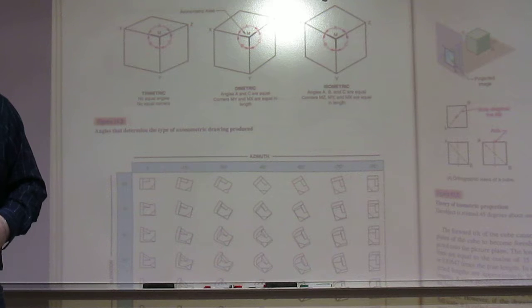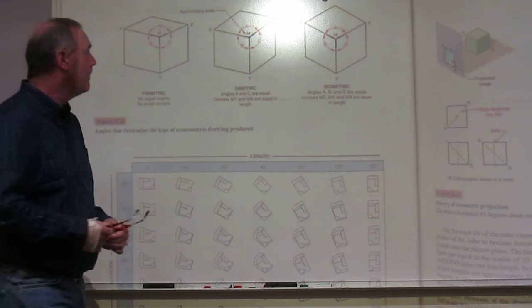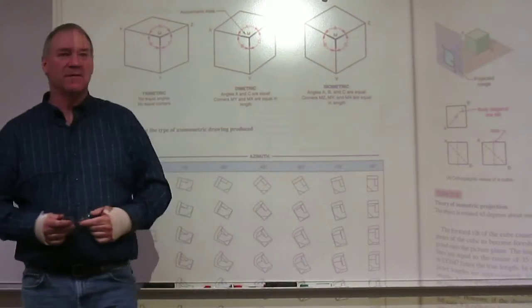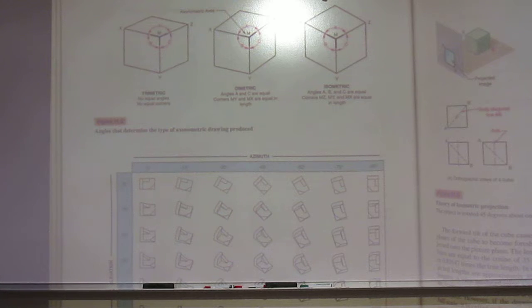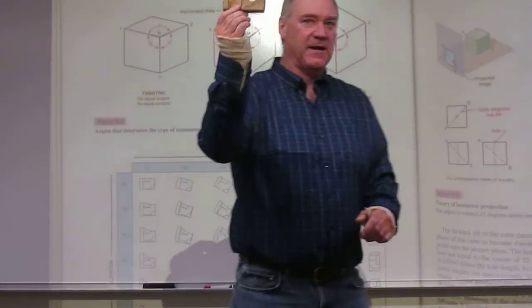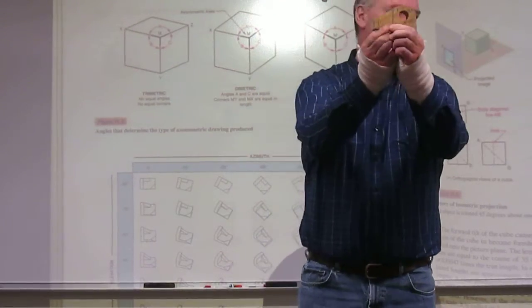What is the angle on there? Angle ABC. Remember, it's a full circle, 120. Now, how they get that is they're using orthographic projection to produce this. Remember, you'll have to do multi-views, but the rotation angle to create an isometric is, you take an object, you pick a front view.